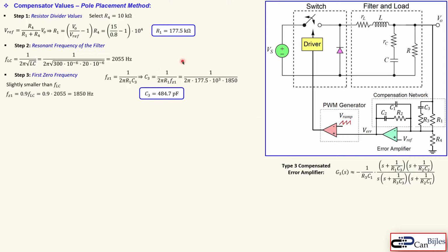Now let's bring here and then create some space to calculate the next part, which is the second pole frequency, because the first pole frequency is 0, we know that, because it's at 0 hertz or 0 radians per second, and the second pole frequency is 1 over R3 C3 in radians per second.